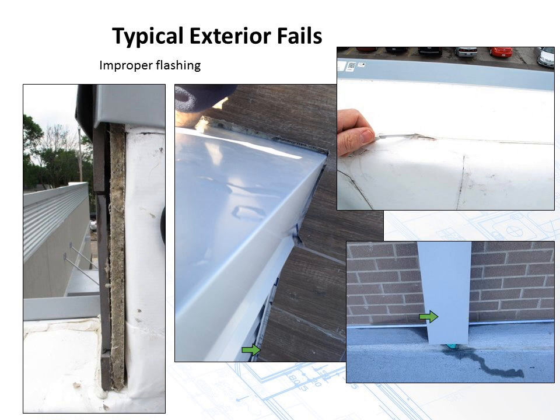You can also see here where water's in the wall, not just in the tile installation on this project, but obviously also in the whole wall system because it's just not properly detailed. This parapet cap, in my opinion, should come over the whole parapet, not just this area, because you can see where there's a gap there. And you can imagine how much water is getting in right there. How about this area where it drips going right into the wall? This is one project. We see things like this on a lot of exteriors, unfortunately.